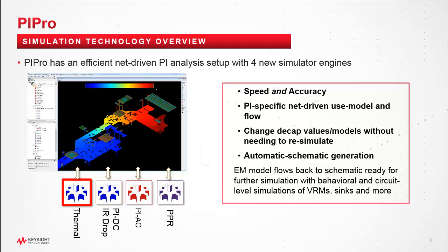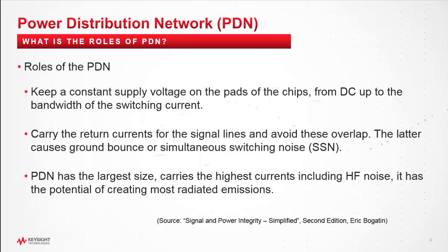PIPro in ADS has a very efficient net-driven PI analysis with 4 simulator engines, which offers you speed and accuracy, a completely net-driven use model. You could do decap value optimization, automatic schematic generation, etc.